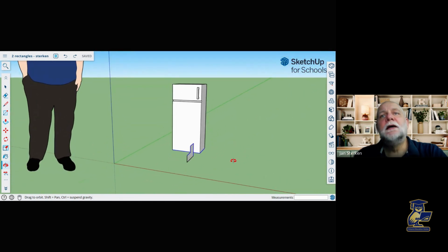Okay. So when you select using the select tool and you select from left to right, it creates a window, and that window will select anything inside of it, but not things that cross through it. If you select, though, in the opposite direction, so from right to left, note the dotted lines on the window, it will select things in the box and things that touch the box.